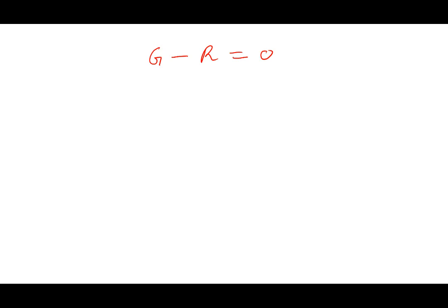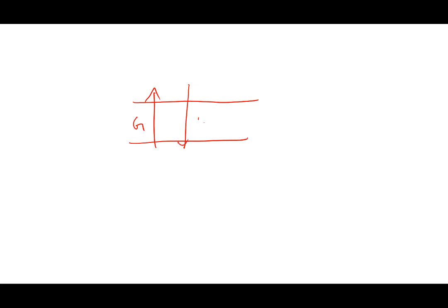Which means that this is actually a dynamic equilibrium. Carriers are continuously being generated and they're recombining. Okay, so we have a continuous process here. You have a generation rate which is happening and you have a recombination which is continuously happening, and the two balance each other, G equal to R. At equilibrium, the two are balanced with each other.